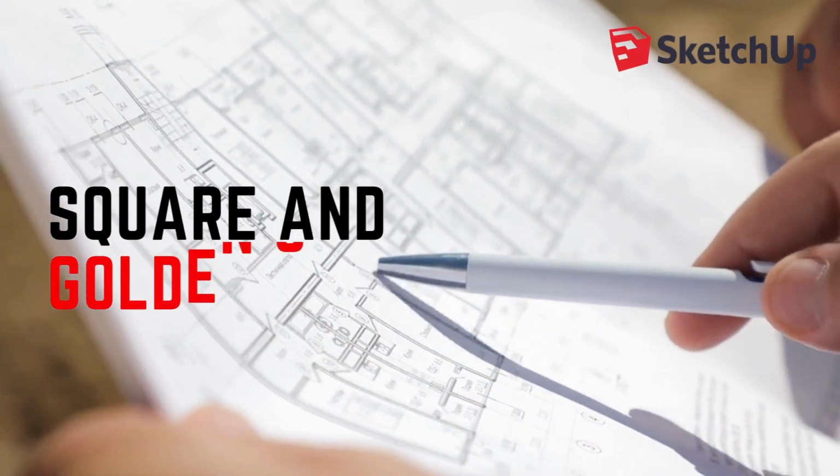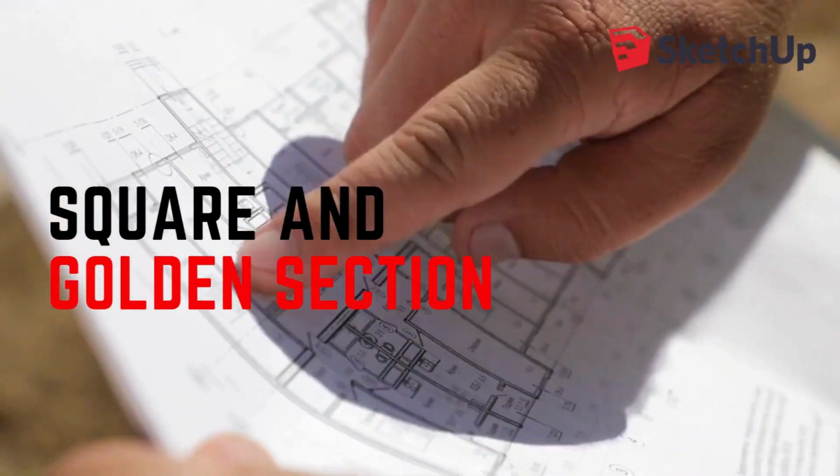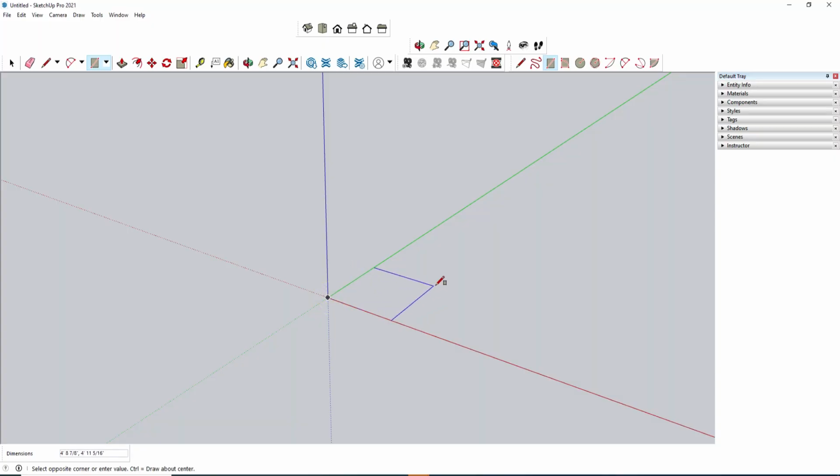Square and golden section. Simply activate rectangle and start drawing. SketchUp lets you know when the cursor is in a position to create a square. If you click when you see the indicator, you'll create a square.